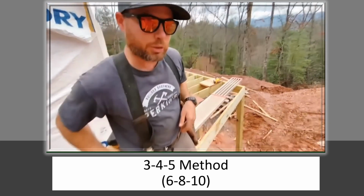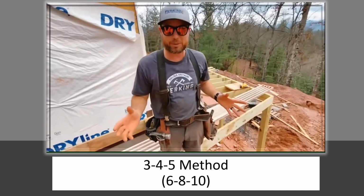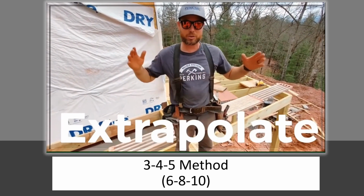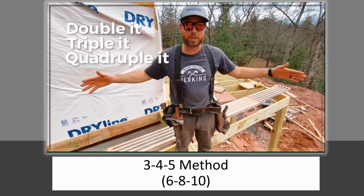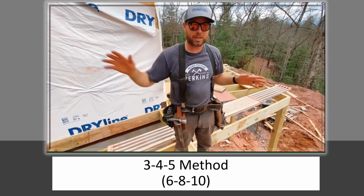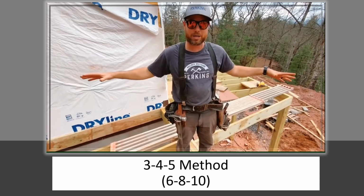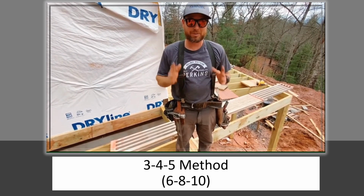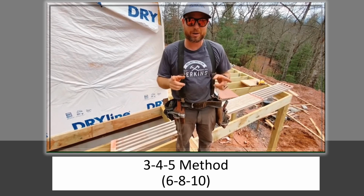So this trick can be used for all kinds of stuff when you're building houses. You can extrapolate that 6, 8, 10 out. You can double it, triple it, quadruple it, and you can pull a huge triangle to get things square, including a whole foundation. We use this all the time when we're building. If you learn this trick, you'll be very glad you did. You'll be able to build things square, which is awesome.